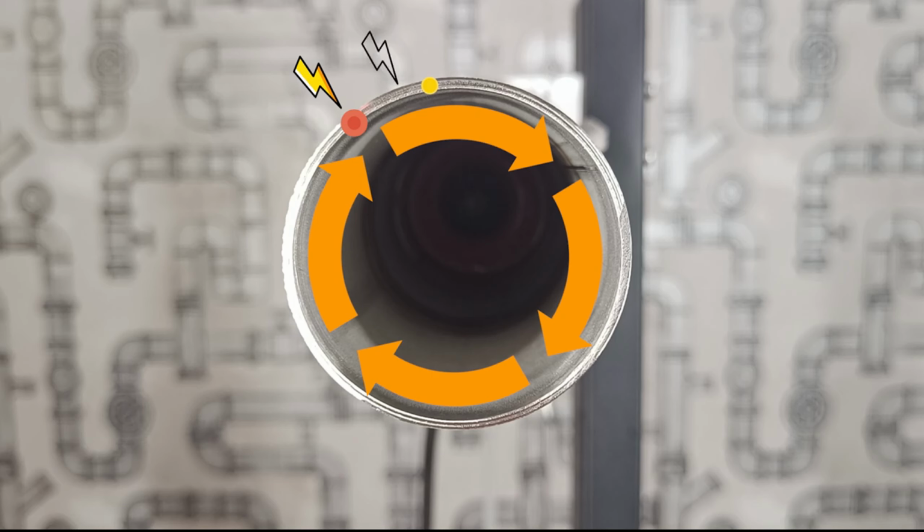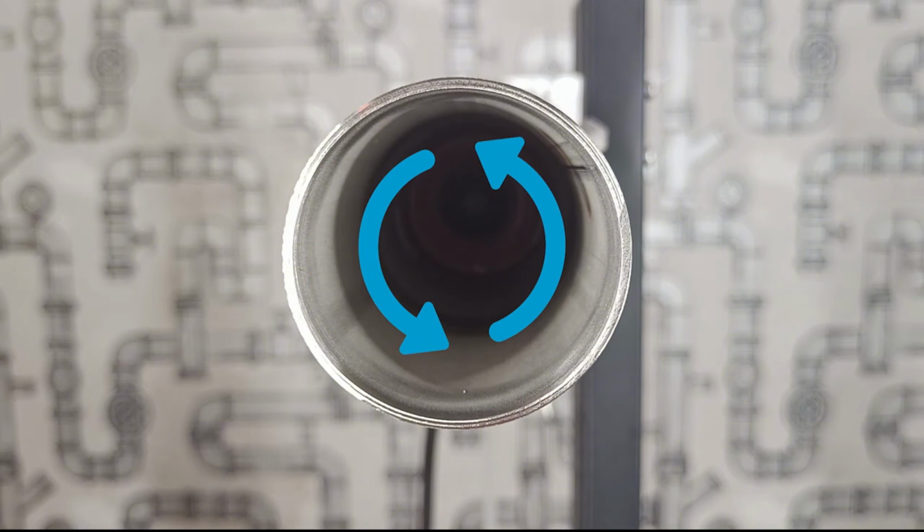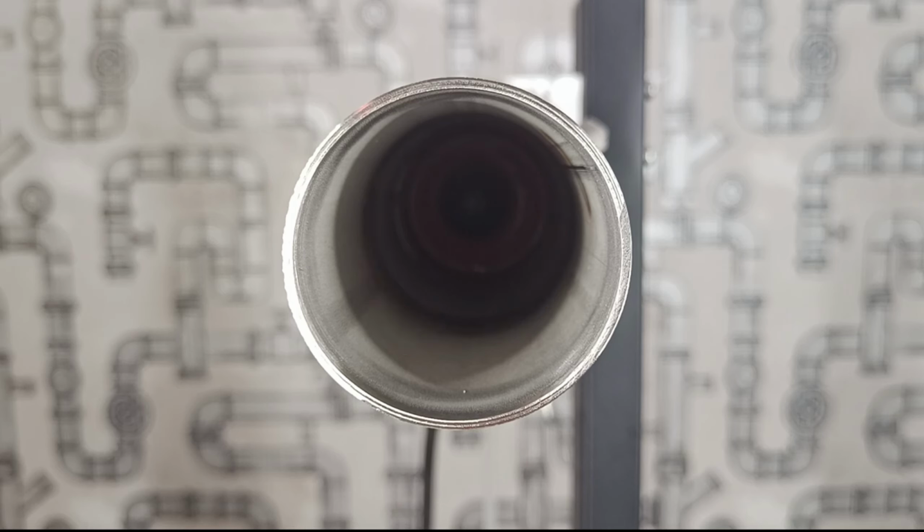Stop pulse and stop welding pulse: the stop pulse sets the arc removal point and the stop welding pulse sets the duration. Rotation direction determines the direction of the head's rotation. Gear ratio: different heads have different gear ratios. Set this accordingly.